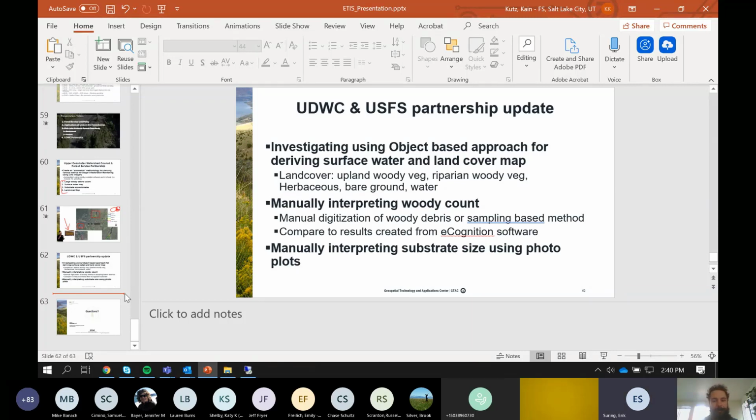Any tips on bringing those two image sets together, like making sure that they're overlapped with one another? I guess if there are any tips on orthorectifying thermal imagery versus typical RGB imagery. Thermal imagery tends to be, just from experience, more difficult because of the nature of thermal sensors. They don't tend to collect imagery at the same resolution as spectral, so you're trying to work with fewer ground control points to tie the imagery to a geographic location.